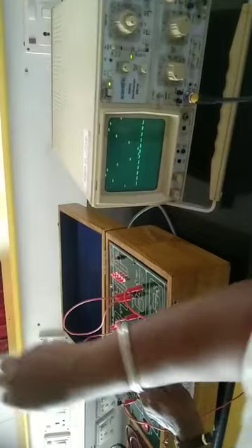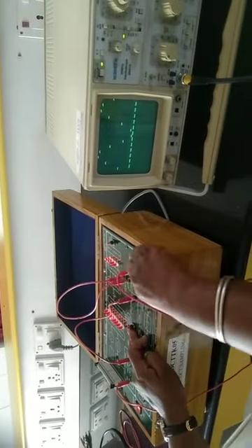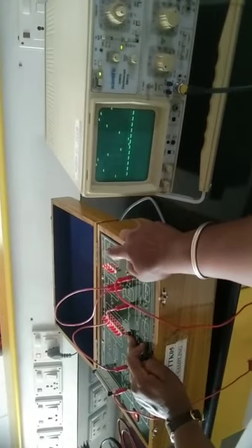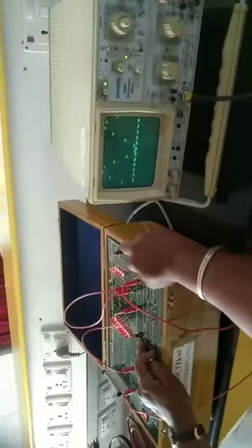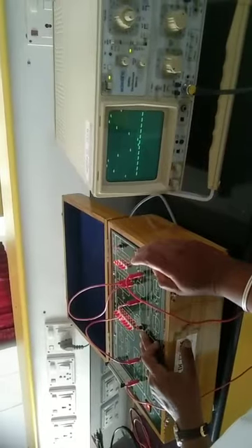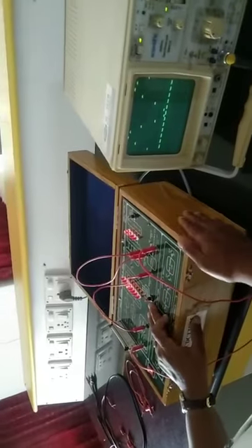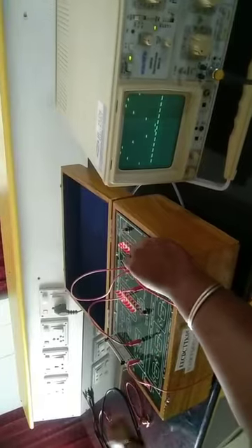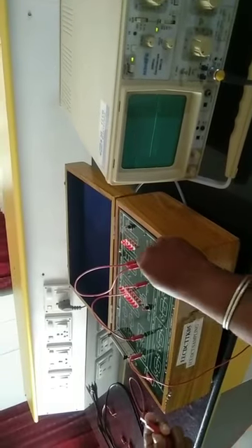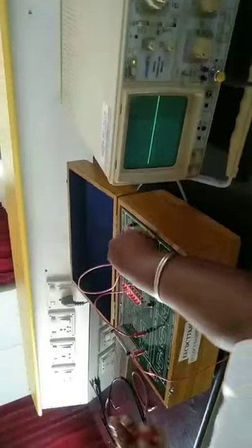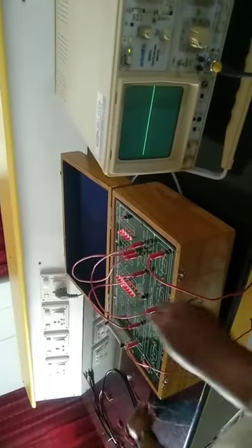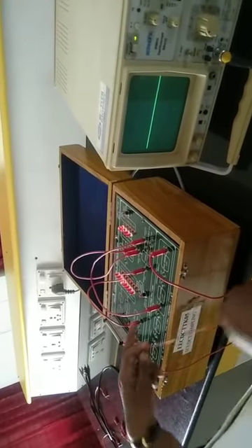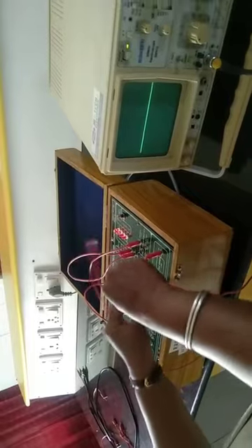From the sample and hold experiment, we can measure three varieties of output. One is the sampled output, the second is the sample and hold output, and the third is the flat top output. Next we have to do the reconstruction. Reconstruction means we have to get the original signal again from the sampled input signal. So we make the connection like this: the sampled output goes to the reconstruction input, and we choose 500 Hz as the input signal, so I can choose this reconstruction condition.